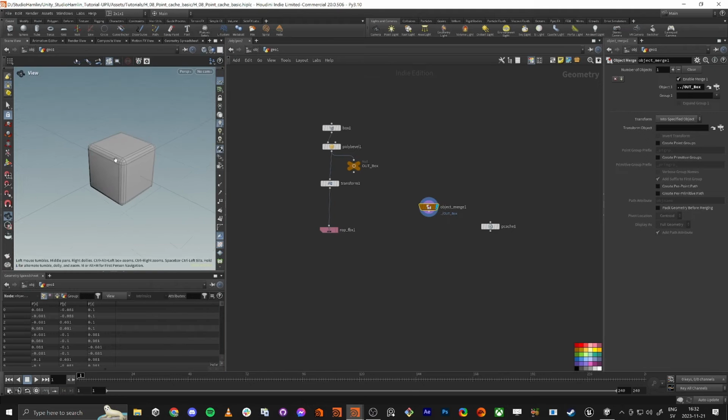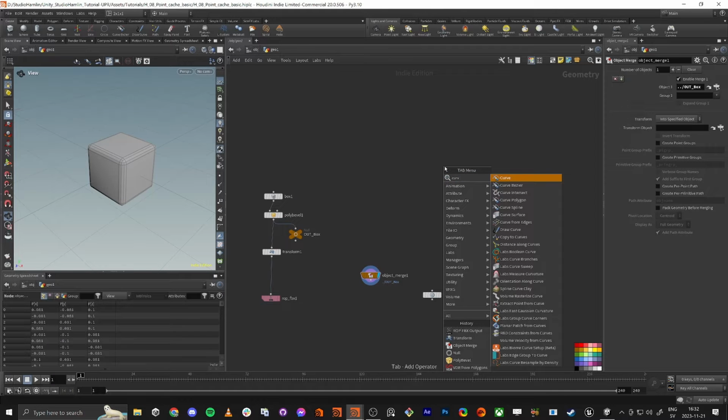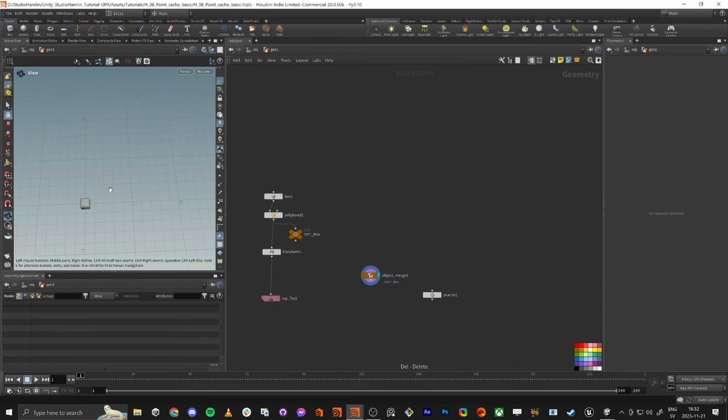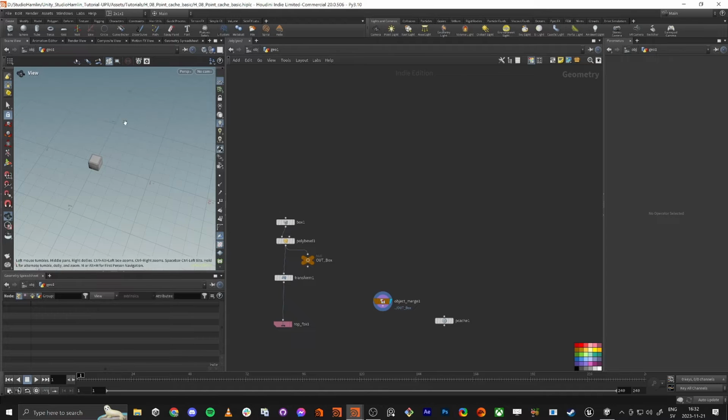And yeah, okay. So we're going to use a curve, and we're not going to use the first one, but the second one, Bezier. And we're going to make sure that we draw from the center in the Z direction. So if we look from the top here, you can see the Z down here. When I hover around, you can see the Z direction is in this direction here, right? So we're going to draw here and do a little curve like this.